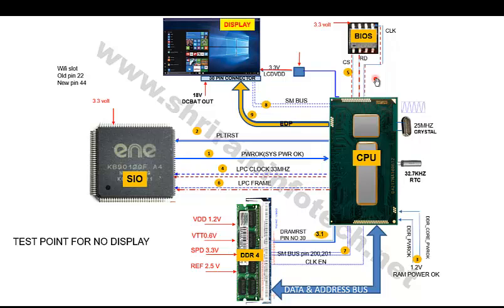In this procedure, all the security features are incorporated into the CPU. The serial number, the model number, the LCD number, the Windows key number, everything is in the CPU. So when you download your BIOS from other sites and flash it, your display won't appear because your CSME does not match the CPU.